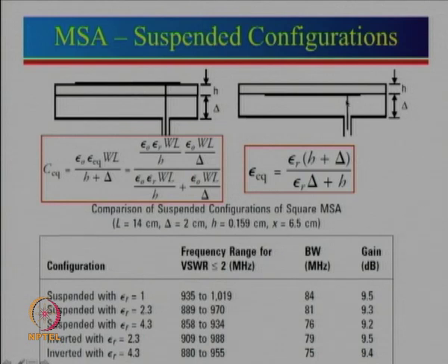So soldering becomes a big issue here, whereas over here you drill a hole, put the probe, it will come out here, and one can solder over here. So sometimes the manufacturing part is relatively easier to do, but if one can do soldering over here or find an alternate way, then this has a better performance, and also the substrate acts as a radome.